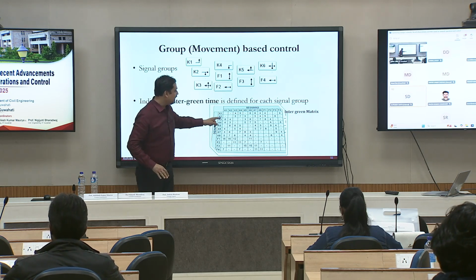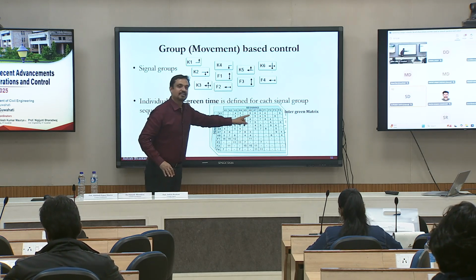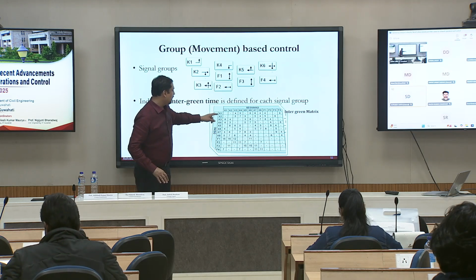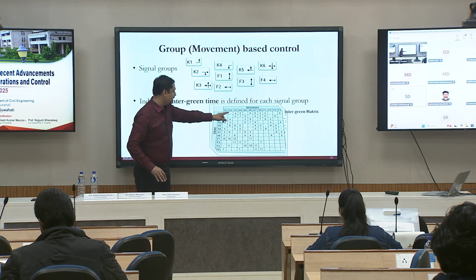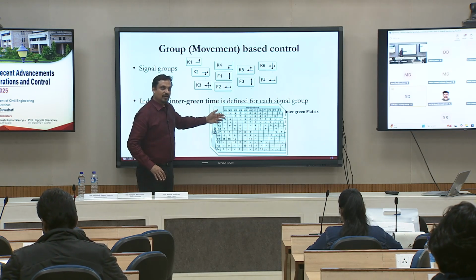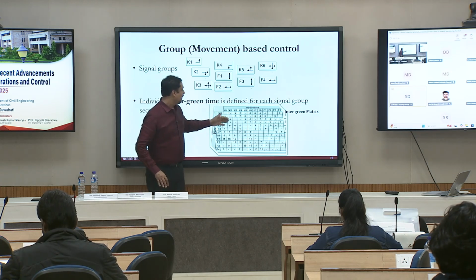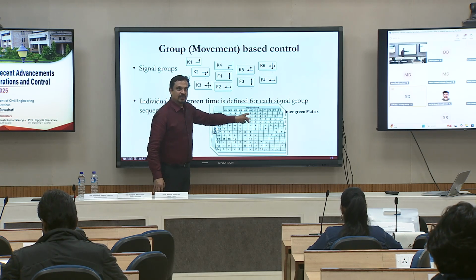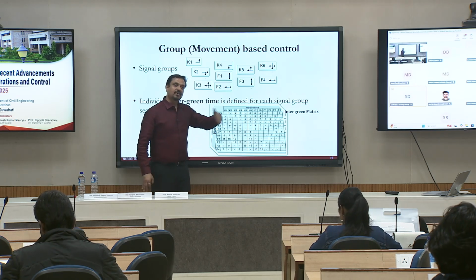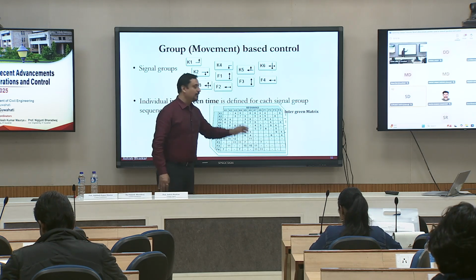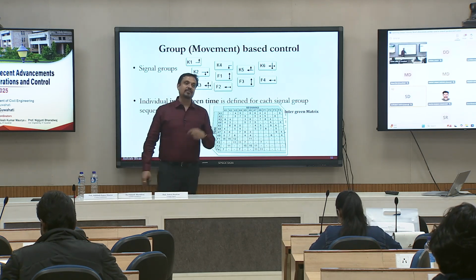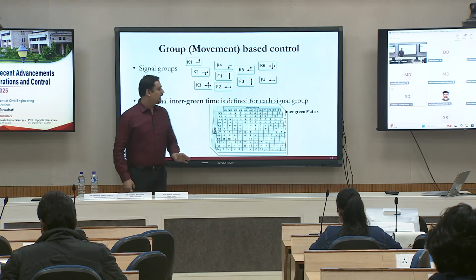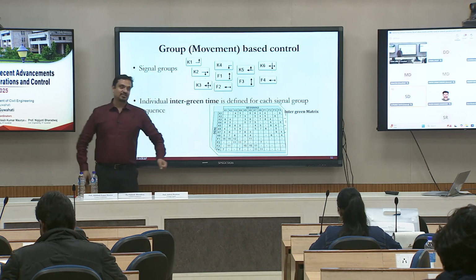Because you can say K1, K2, K5, K6. So K1 and K2 can go together, they are working. Now K1 demand is over and you have to cut off K1. You can select K6, and you can still let K2 run, but if you select K6, it has to start after 6 seconds only. So that's the way you can make the selection.